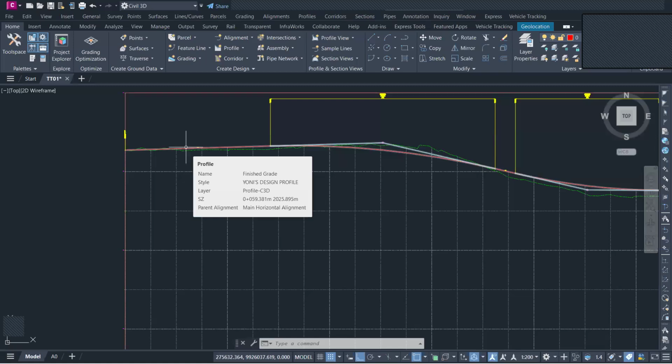You fill. So there is always an assumption that the amount of material you're going to cut is always the same that you're going to fill, which is not true. Because in this case, you are going to do compaction. So we achieve a 95% compaction. So then this means that when you're getting the amount of fill material that you want to bring there, you can play around 110%, 105%, all the way to 110% because of that shrinkage and the compaction that is going to happen there. So that then you compensate for that compaction.